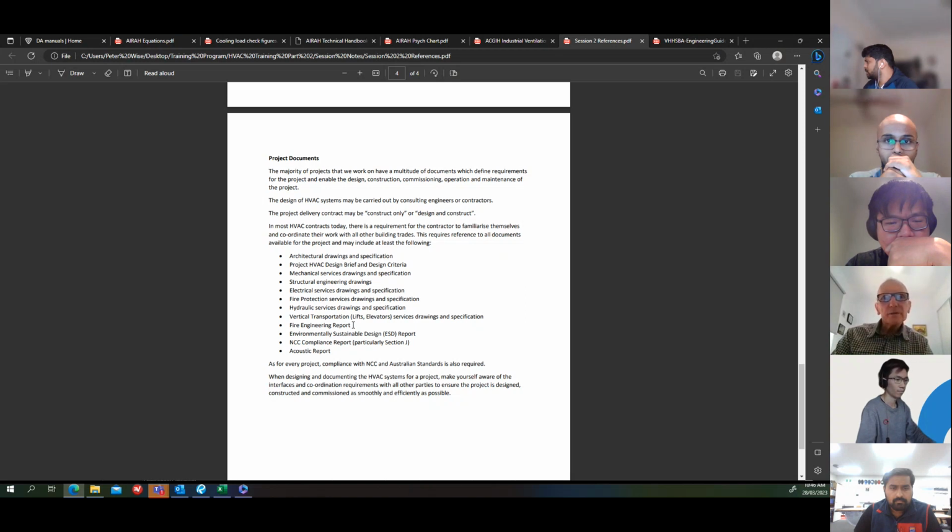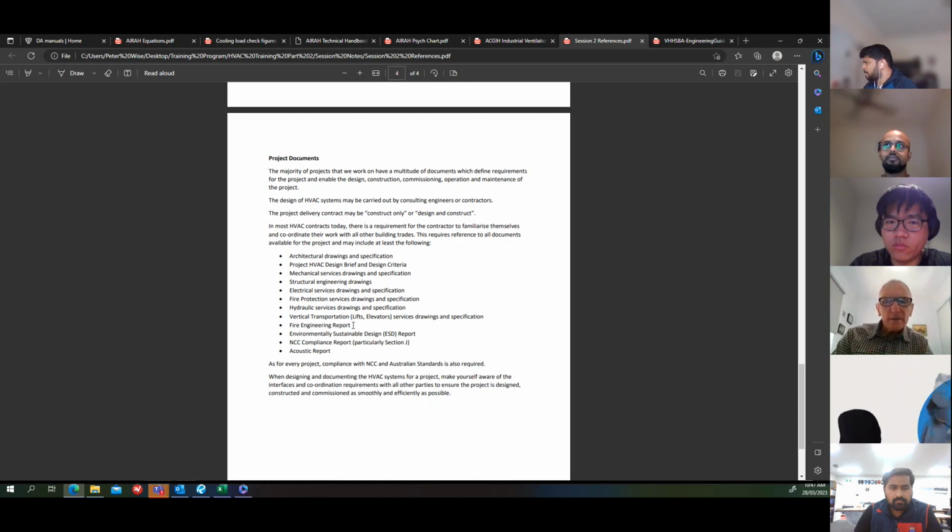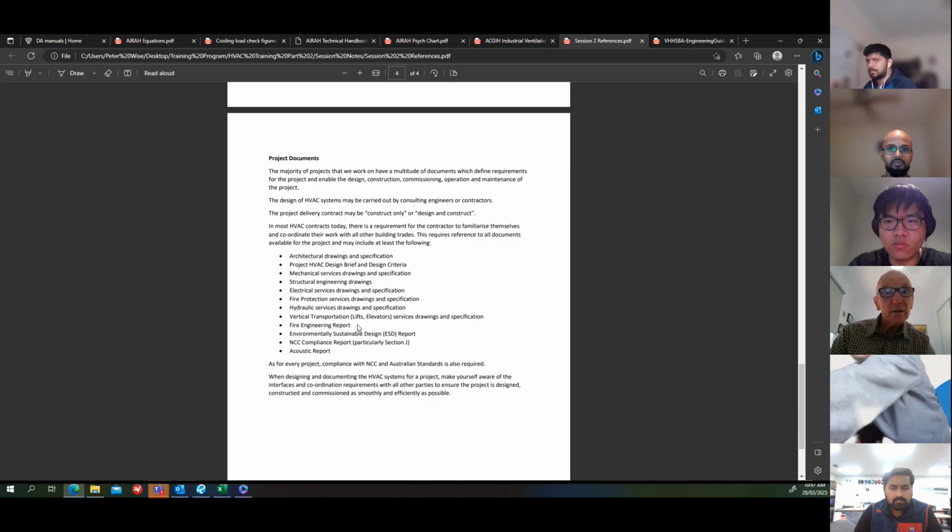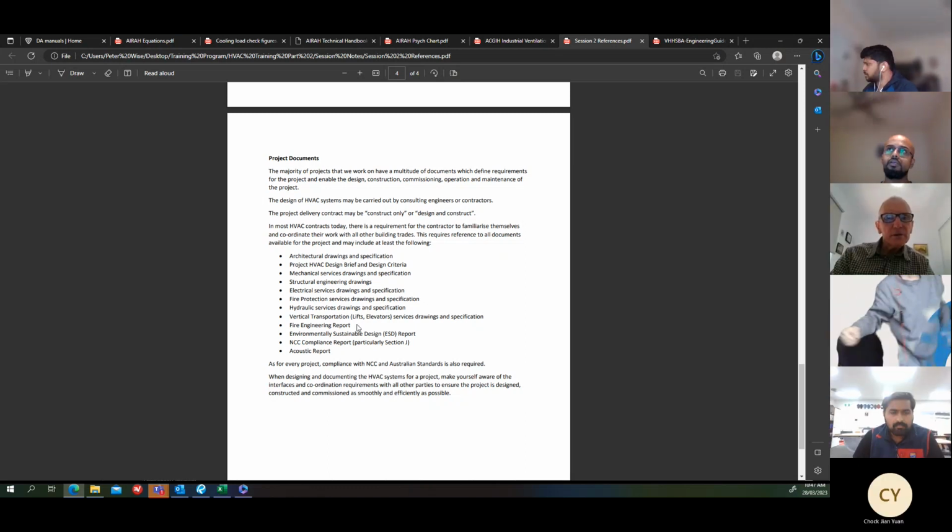There's usually these days a fire engineering report. I mentioned this last week, and I think there was a question asked. If there's reference to mechanical services in the fire engineering report, then you need to comply with that. And that might be different to what is in the NCC or AS 1668 Part 1. But the fire engineer has the authority to come up with alternatives. Okay.